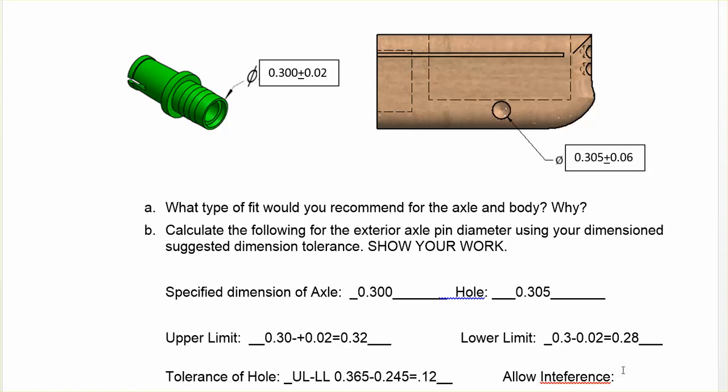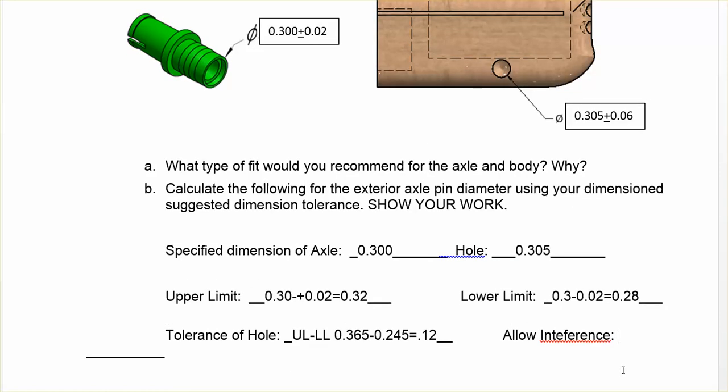This last one right here, this allowance slash interference. This right here was quite some problem for some students as we were going over allowance and interference. I'm going to go down a space here. Our equation for allowance, I'm just going to say A slash interference, was equal to the MMC of the interior feature minus the MMC of the exterior feature.